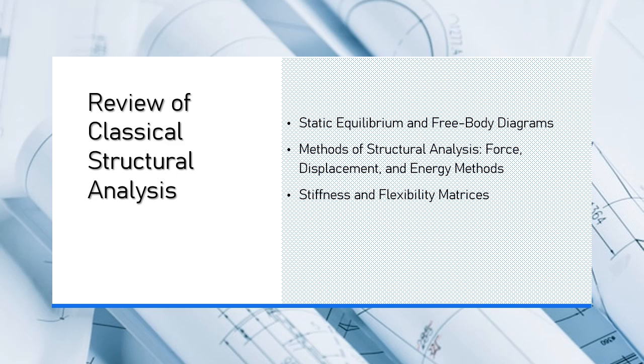Indeterminate structures: in statically indeterminate structures, where the number of unknowns exceeds the available equilibrium equations, classical static equilibrium methods alone are insufficient. In these cases, advanced techniques like matrix methods or finite element analysis, FEM, are necessary to solve the system. Static equilibrium and free body diagrams are fundamental concepts in structural analysis that form the basis for understanding the forces and moments acting on structures.